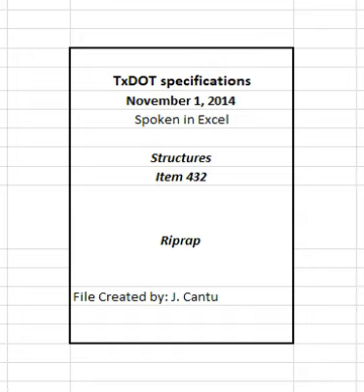When bedding is required for protection stone riprap, payment will be made at the unit price for bedding material of the thickness specified. This price is full compensation for furnishing, hauling, placing, and maintaining the bedding material until placement of the riprap cover is completed and accepted, excavation required for placement of bedding material, and equipment, scales, test weights, labor, tools, and incidentals. No payment will be made for excess thickness of bedding nor for material required to replace embankment material lost by rain wash, wind erosion, or otherwise.